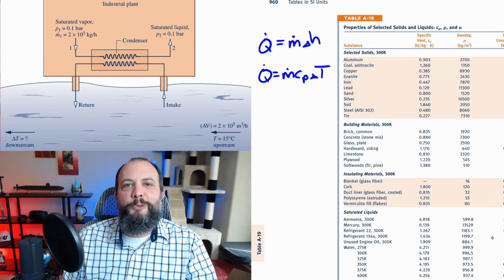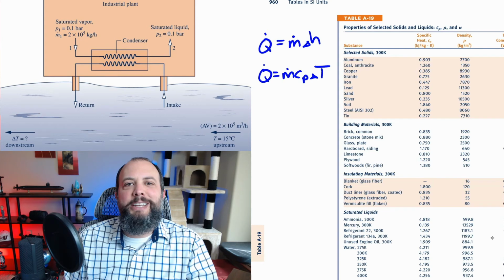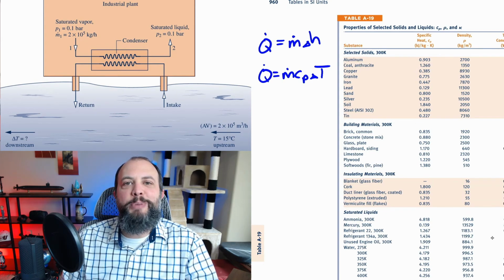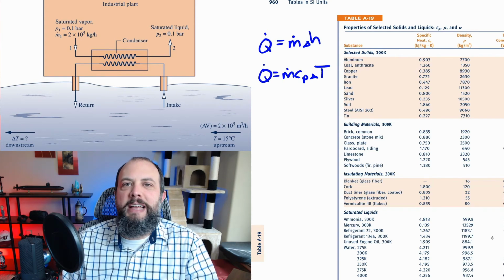so the river water temperature went up about half a degree. We solved this problem using heat as m dot delta H. We could have alternatively used Cp delta T instead, but in this case it wouldn't have actually saved much work.